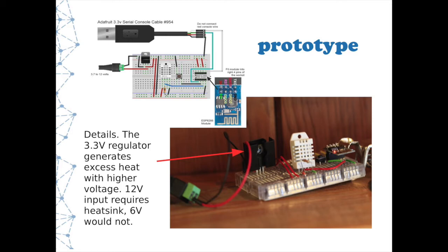And so the danger here is that with a simple regulator, if you don't have a heat sink on it and you're giving it 12 volts and you need to drop it to 3, it's going to burn up that regulator. So you need to know that it needs a heat sink. So all these details can make a difference. When you're exploring and working with these things, it's important. The worst you can do, though, is you burn up a $5 chip. So order in quantity or small quantity, because for that and other reasons.